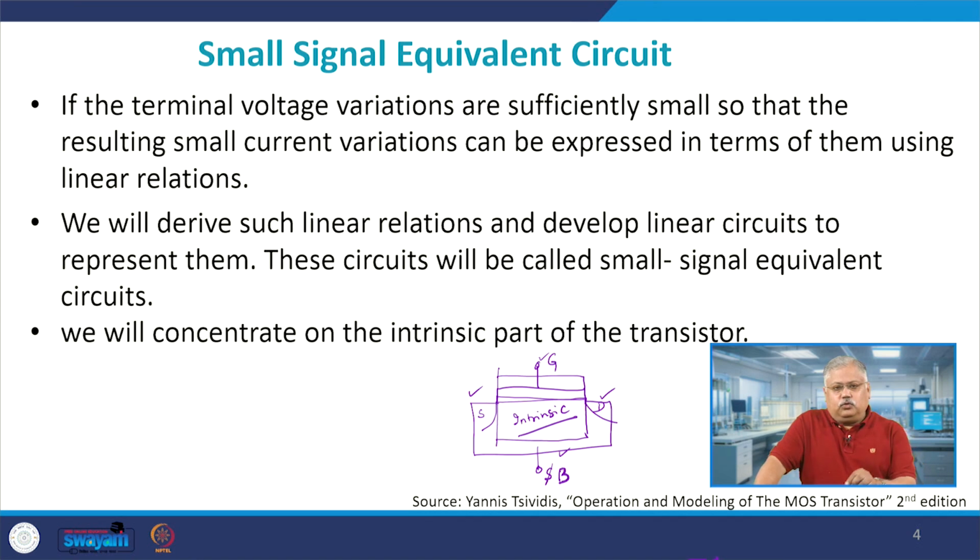So, we are trying to emulate a current source through this intrinsic part, which can be done using the gate bias, and we know that when Vg is greater than the threshold voltage of the device, there will be a thin inversion layer here which will result in the current flow. Now, we define this to be the intrinsic part, and the other part is your extrinsic part, right.